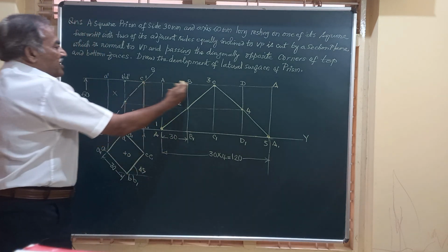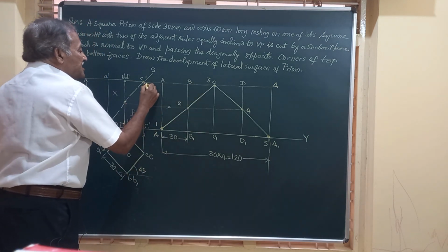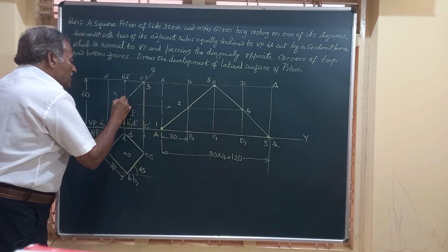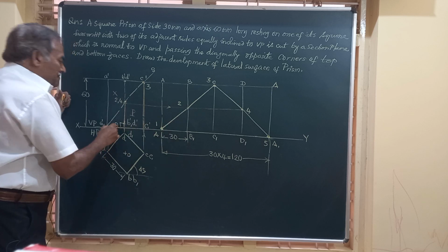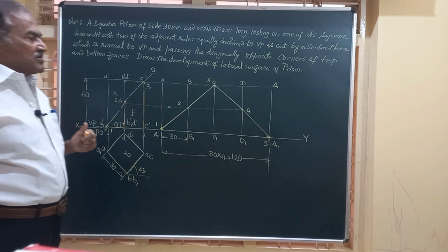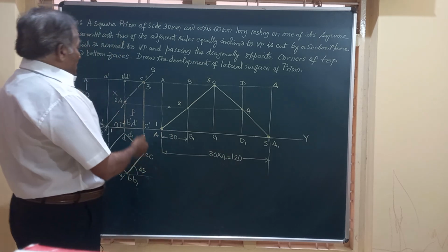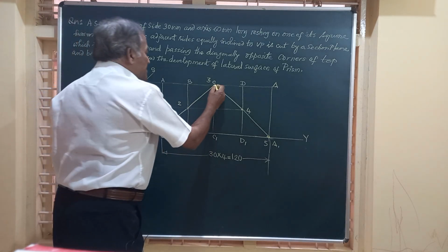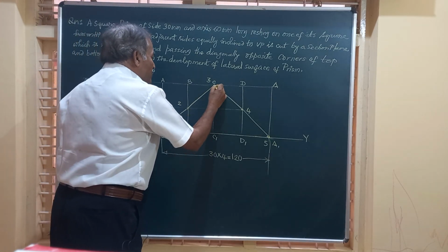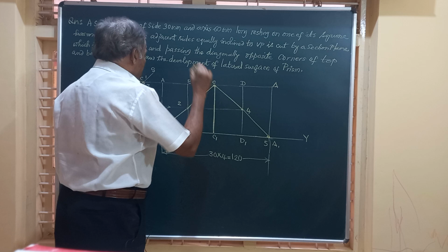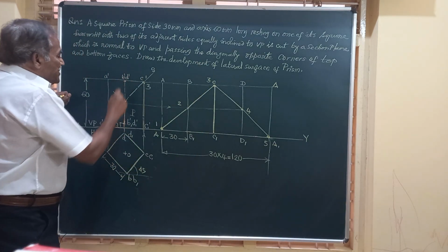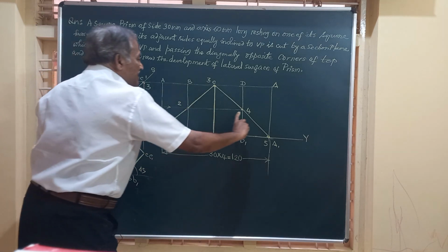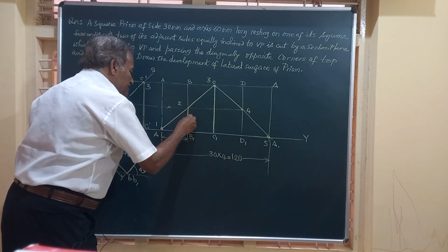Let me transfer these points on to the front view. This is 3. On this line, 2 and 4 at this. This is 2, 4 and 1 is here. So I have marked all these. Friends, in the front view, the vertical line CC is retained. So this has to be shown by a full line. This is existing. And on this BB and DD, this height is retained on BB and on DD. So darken that.